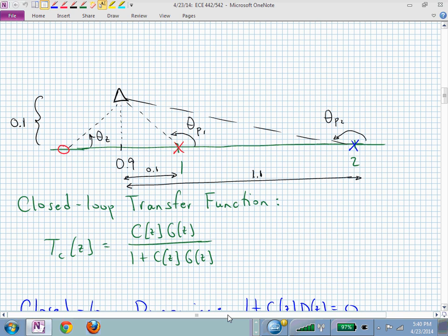So if that triangle would have resulted in the angle of theta of z being bigger than 135 degrees, then we would say, whoops, we don't have a solution for those triangles. We need to change the location of those triangles. Those are not going to allow us to have a stable closed-loop system. Is that clear? And you might run into that. You might propose triangles somewhere that actually cause your system to be unstable. And then, or it may not be a valid solution.